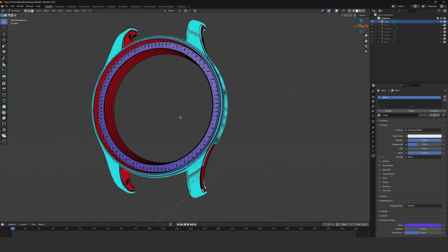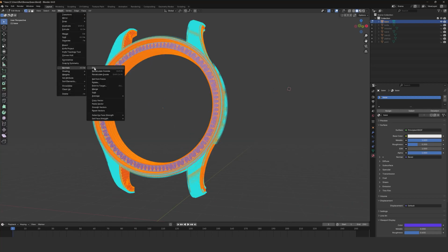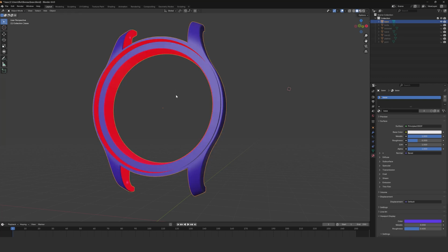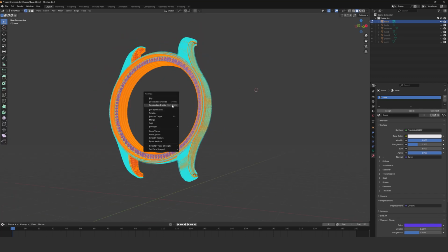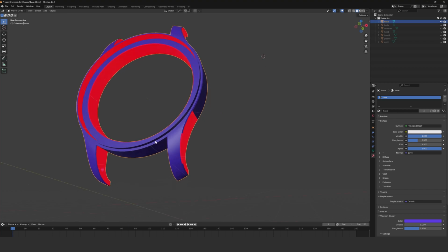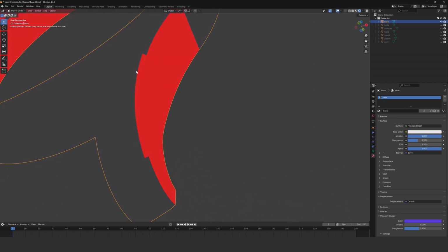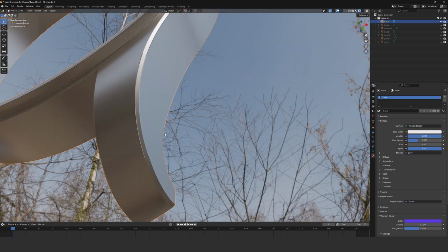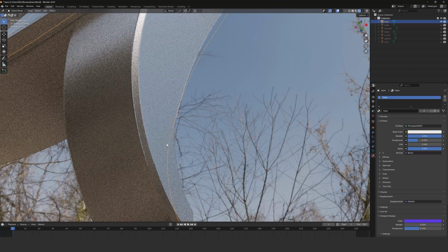You might say, just recalculate normals in Blender using Mesh, Normals, Recalculate Inside or Outside. Let's try, but as you can see, it doesn't solve the problem at all. How does this issue appear in rendering? Very simply, zoom in on an area like this, disable Face Orientation, and you'll clearly see rendering artifacts where the faces were red.